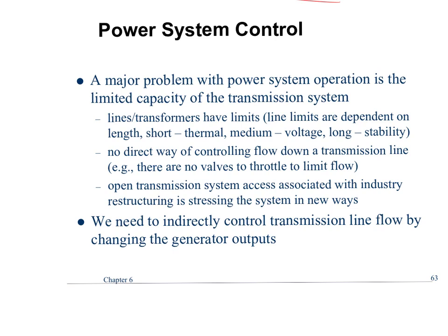So you can indirectly control. You're not directly controlling real power. You're just controlling the phase angle and the voltages and hoping that you'll be able to do it, which you can do a pretty good job. But again, it's not like you're putting more water into a tank or less water where you can control the level directly. This is all indirect.